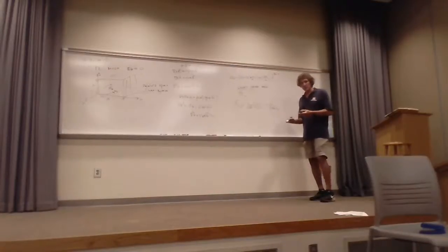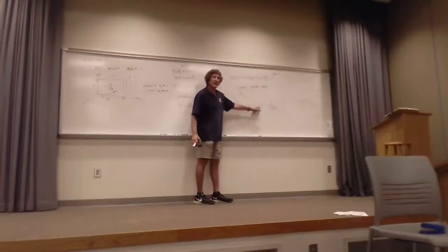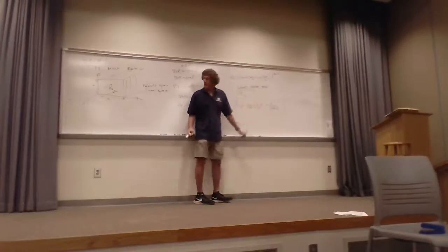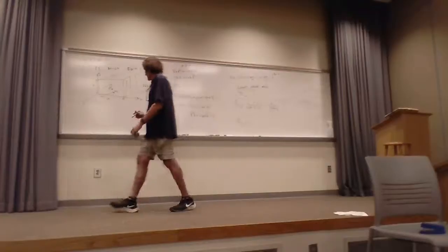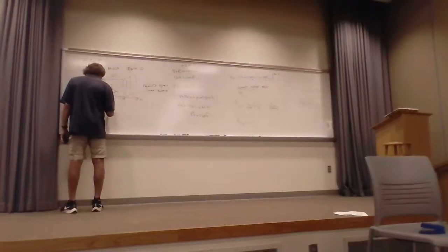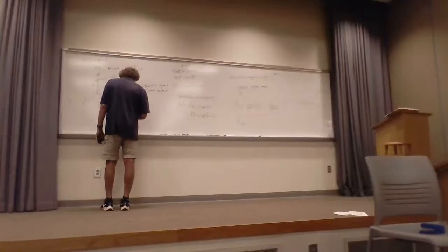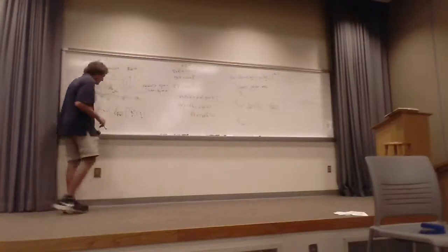All right, that's the 1-0 mode. What's the 2-0 mode? fc 2-0. Well, instead of 1 there, I'd have a 2, wouldn't I? I'll put the general formula here. fc in general for the M, N mode is c over 2 square root of epsilon relative, times the square root of M over a squared plus N over b squared. That's it, period.